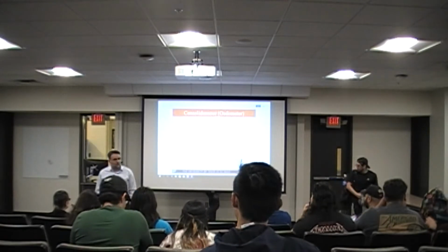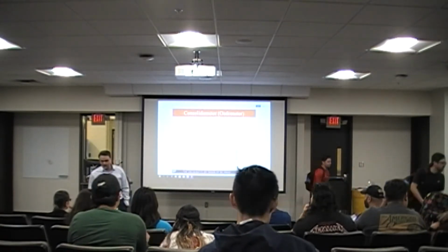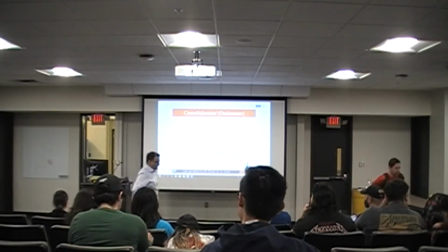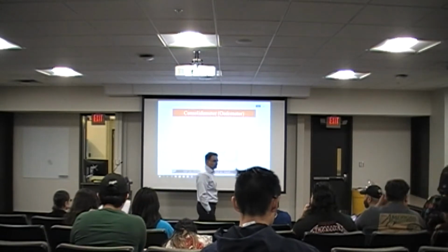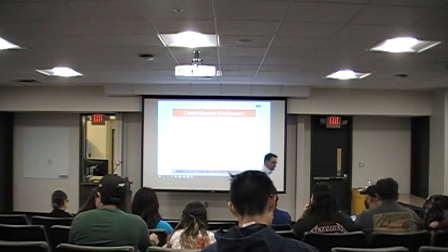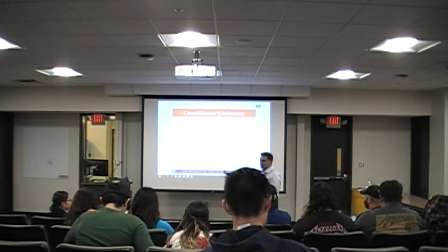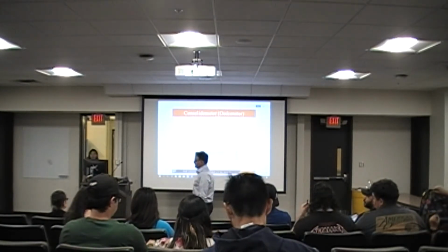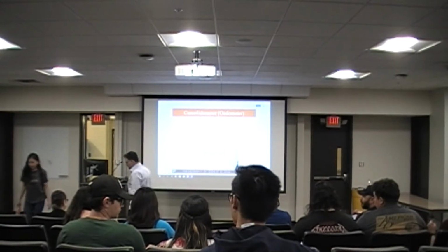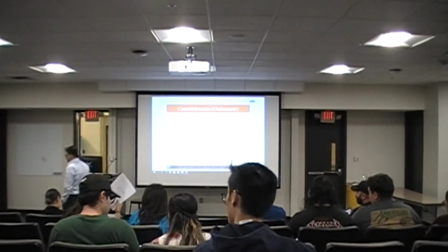We also talked about the non-destructive test. Remember, we talked about the nuclear density gauge, and the nuclear density gauge was essentially a non-destructive test that you can use in order to get an indication of the density of the material, right? So you can get information about the density, you can figure out what the layering of the soils is, and based on that information you can calculate the geostatic stresses.